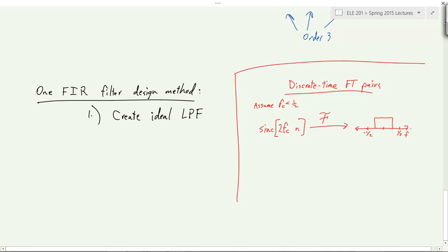So really, this is the Fourier transform. It repeats. Right? It has to. In fact, we could have known that, because you could have said, take a continuous time sinc and sample it. The continuous time sinc is band limited, because the rect is bounded. So when you sample it, you won't get any aliasing. The copies will just be separated. Nothing weird happens, unless fc was too big.